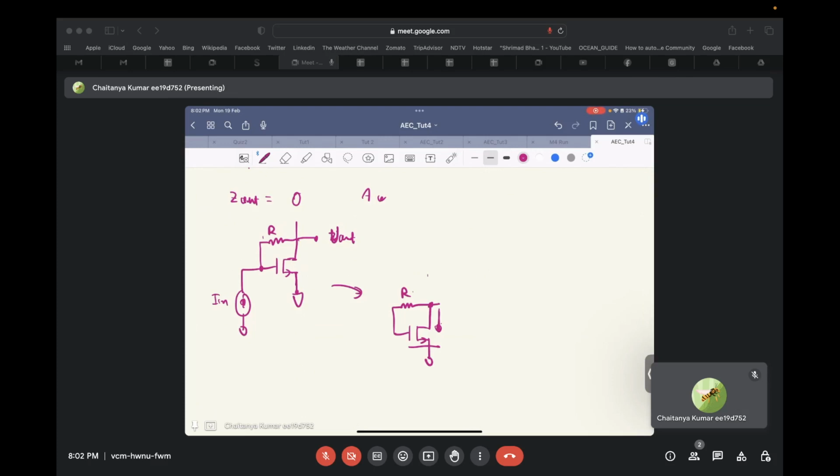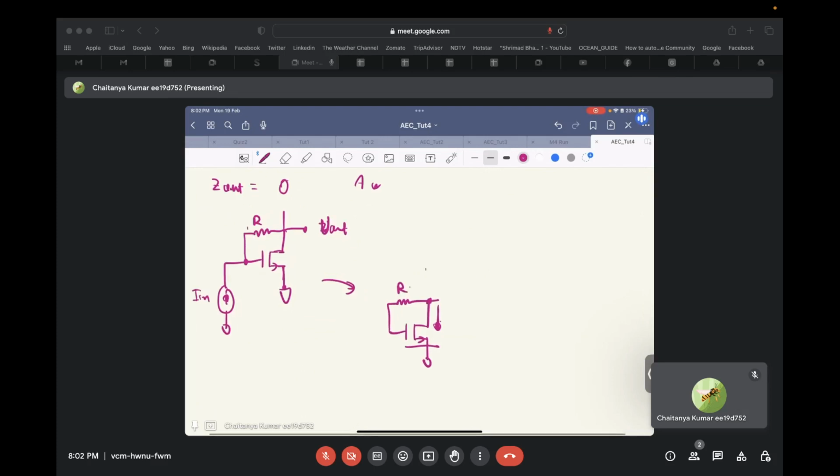So that's its job, if we are saying that the MOSFET's drain is open circuit in incremental analysis. Let's say this voltage V over here tries to increase. That means the gate voltage Vg also tries to increase. That means there is some current that tries to flow through this transistor, that is gm times Vg, and since there is no other path for the current to flow, it will start pulling the voltage.